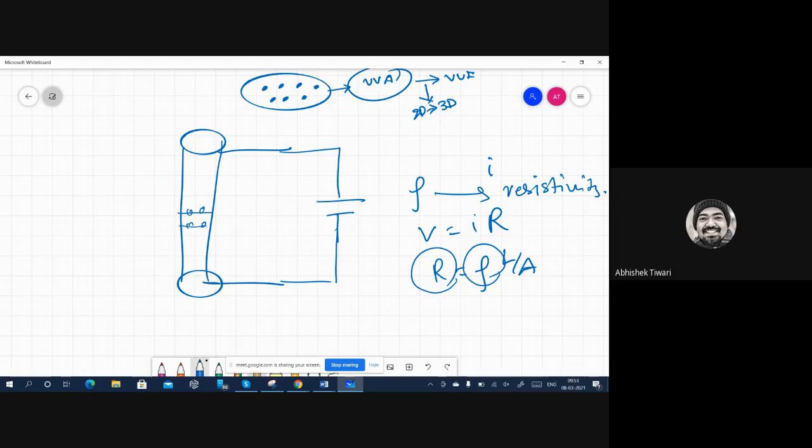And this change in resistance can only be a representation of damage, because resistivity is a material property that is not going to change. Length, we know by what amount it is changing because we can see it, we can measure it. The damage which is happening inside, that we cannot measure. So we are not bothered about L, A or rho. We are bothered about how much is the change in the resistance, and that is straight away related to the damage parameter. And you can do this, and you can also find out the kinetics. So that is the part of how we get the kinetics.